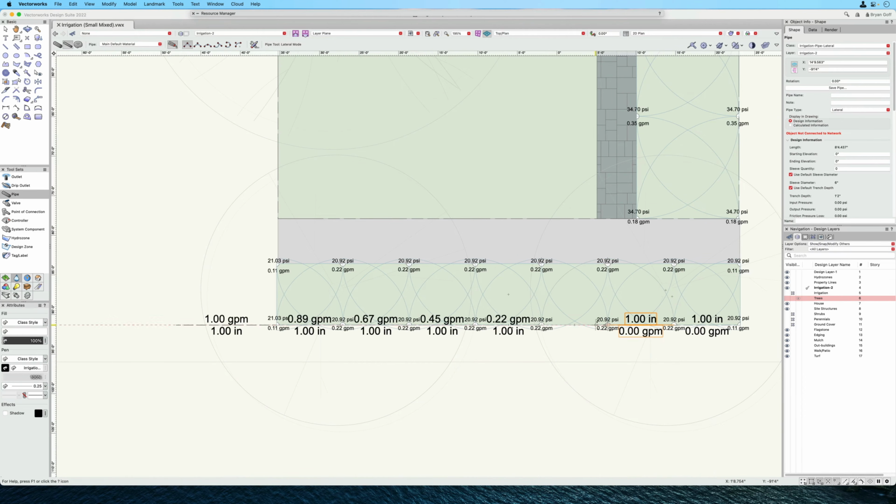All right, I'm going to purposely leave this open here. I'm going to go up to this top row. A nice one is if you do have a straight row, we can come up above and there's this little glue bottle. So this is the auto connect mode. This allows me to draw one line across all of these. And you'll notice it makes individual connections to each of those. But you'll also notice they're not giving me a gallon per minute because I'm not connected to that main network.